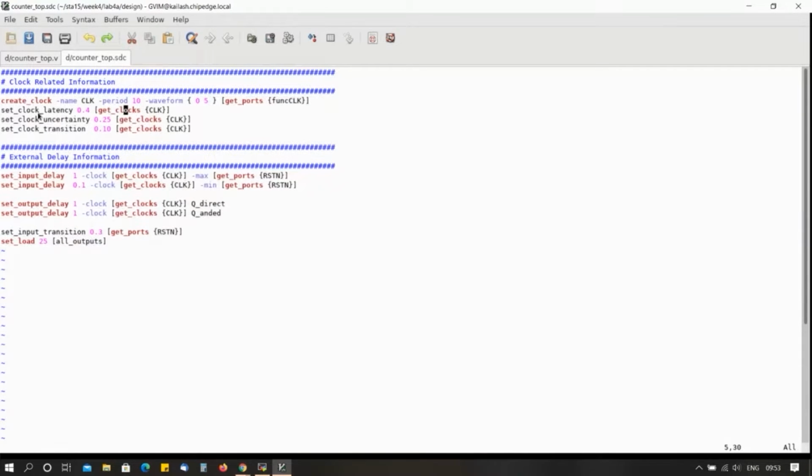So that's why we write these constraints and store them in a .sdc file and consider it as an input. Or else you can give it in parallel along with your tool; this is one way of providing the inputs. Some of you may ask, if they give you only RTL and some SDC, how can we give the input as SDC when we are supposed to write out the SDC? These are design constraints, so you can give them as input, but after applying them to the design, you write them out.